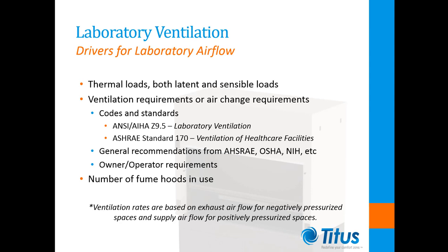Determining the airflow rates for laboratories begins with looking at the thermal loads in the space. At a minimum, we need to supply enough air to maintain space temperature and humidity within the desired range. Independent of thermal comfort requirements, the minimum air change rate needs to be established next. There are lots of different references that address unique requirements for lab spaces.